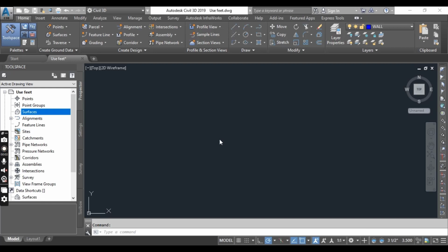Hi students, many times you will receive files from people who don't use Civil 3D as their design platform. When these files are opened for the first time in Civil 3D, the template will create standard settings and styles. For this reason, when you open a file within Civil 3D and access the Settings tab of Toolspace, you will see that for each object a standard style is defined. This style is created for both the object and labels and defines all of its properties using layer 0.